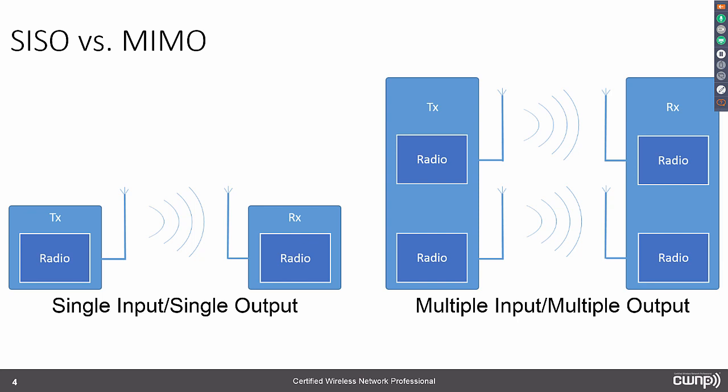So we can look at the received preamble. That's the early information that comes in on the antenna before any actual frame information is received. And that can be used then to select the best signal and therefore the best antenna. And this is sometimes used in older devices, and it can still be used in newer devices today when communicating with single radio systems.